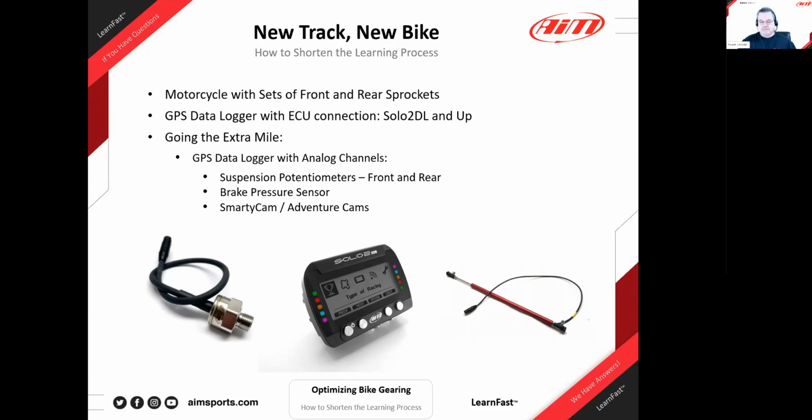The reason I have the cameras here is not so much for choosing the right line or things like that, because you do see that in data. I would like to use it that way, but we don't have it at Mode America, it's not allowed. But I'd like to have it to discard some of the laps where maybe we ran into traffic. Like if we're seeing something in the data, somebody let off the gas too early, or had to slam on the brake at an area that's not really expected, you're able to confirm with the SmartyCam or any adventure cameras that you have that that person ran into traffic or there was a bump. It's really interesting to know what happened, and in that way you can not overthink that lap, throw it away, and move on to a new lap that actually has data that's of quality.